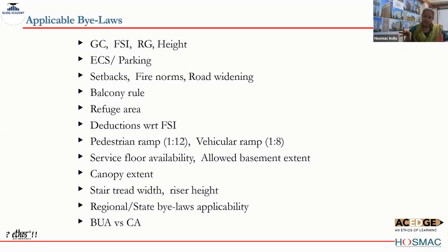One will be allowed to build a service floor, which is an uninhabitable floor, at 2.4 meters only. 2.4 meters is 8 feet, which means that under the beam, you only get a clearance of 1.8 meters from an unfinished floor level, which also does mean that you cannot live in this floor. You cannot walk very well in this floor. And this is supposed to be free of FSI.